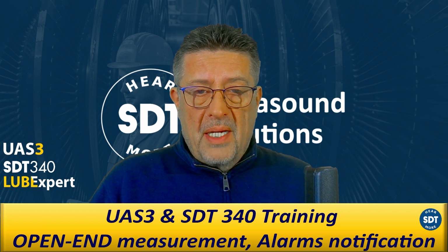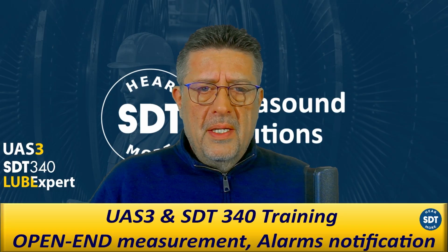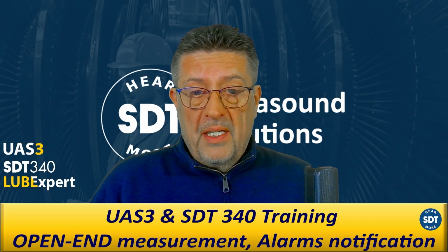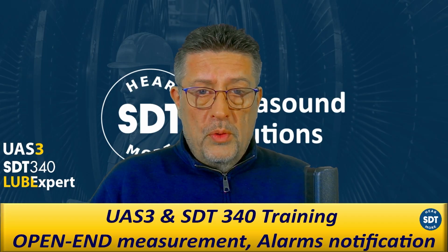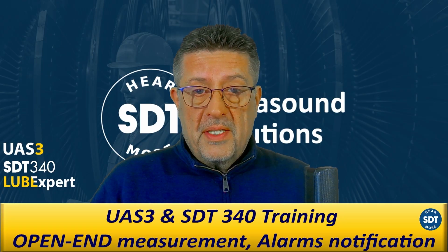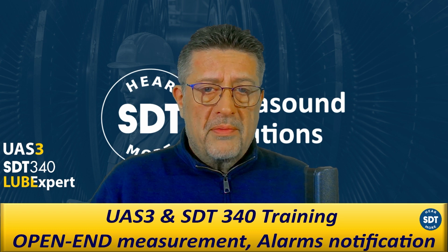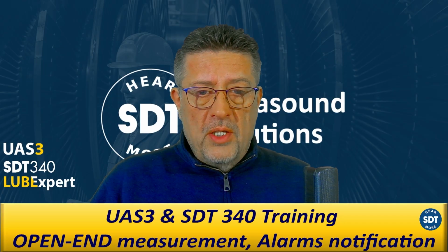Let's take steam traps as an example. If we set the time of 20-30 seconds, it's not necessarily enough because it's a random operation on demand, and a purging process can be after 1 minute, 1.5 minutes. On the contrary, if we use the luxury of the long acquisition time in SDT340 and set it to 5, 6, or 7 minutes, it may happen that you record the cycle after 20-30 seconds, but then you have to wait for a long time to collect the measurement and save it. Of course, that's not the only example.